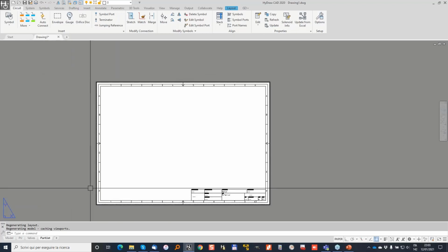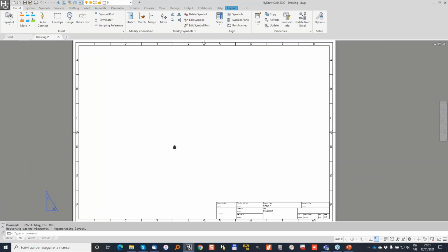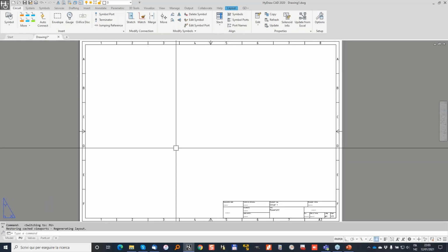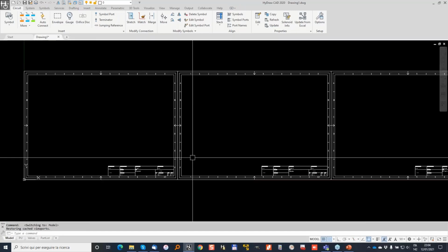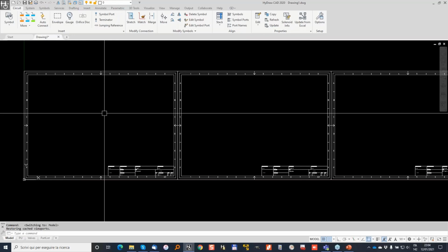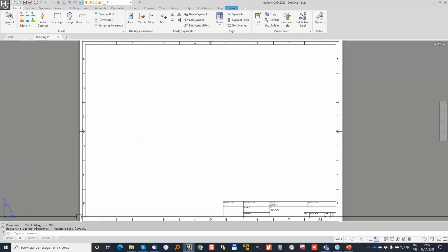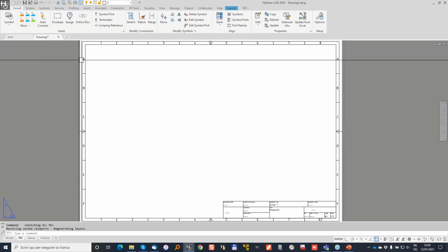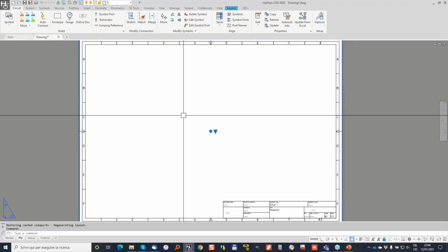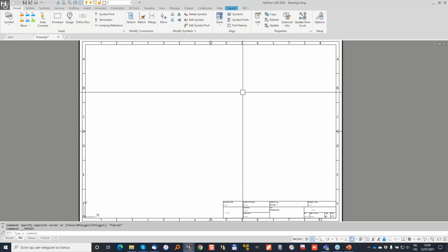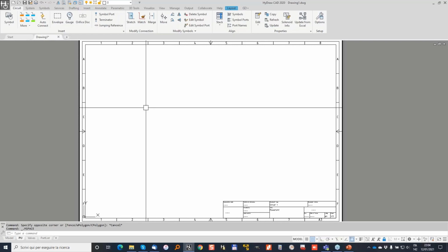One piece of information that, if you are not very familiar with the AutoCAD environment, you may not know: it is possible to work directly in paper space. Although in the model space I have 3 frames, and I will physically place 3 parts of the diagram in these 3 frames, I can also draw directly on the main page. It's important that you enter what we call the layout, a viewport. I double click inside my viewport, and now everything I draw here is like drawing in the model space.